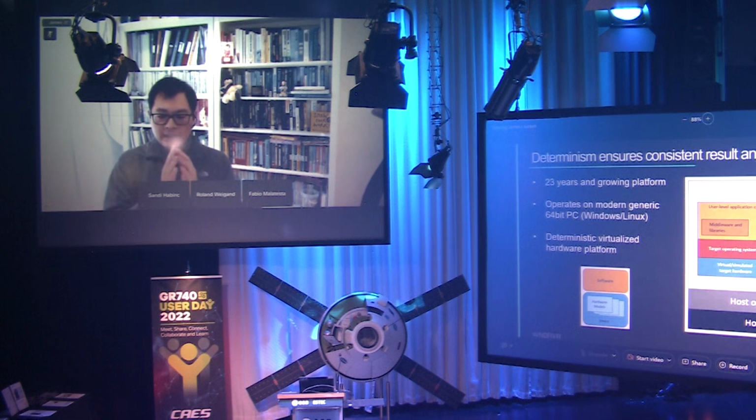Simics has been around well before we started to use it. It started in Stockholm with a company called Virtutech 23 years ago, and it's still a growing platform. Simics is a standalone application that runs on a generic 64-bit PC, a modern PC running Windows or Linux, and it's there to provide a deterministic virtualized hardware platform.